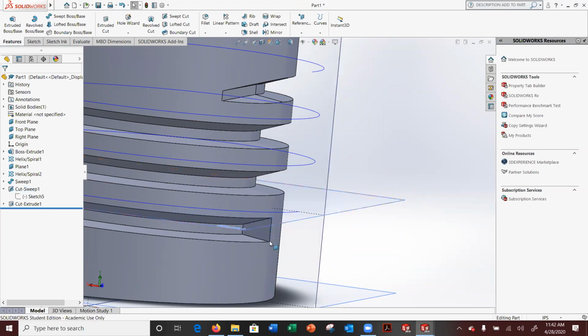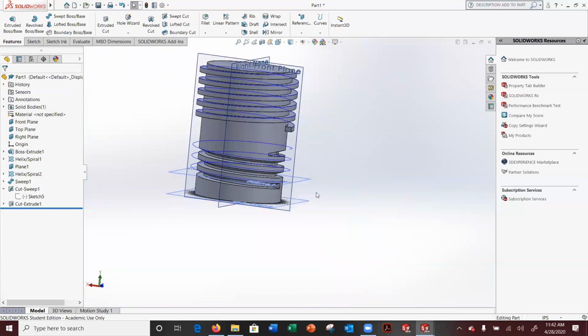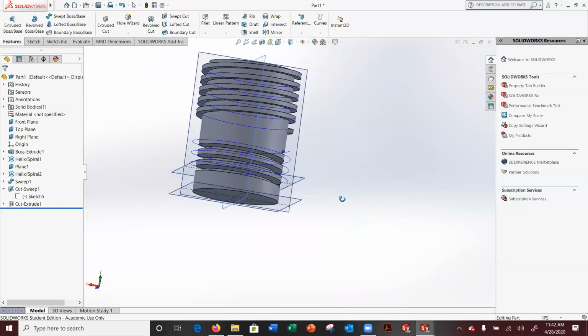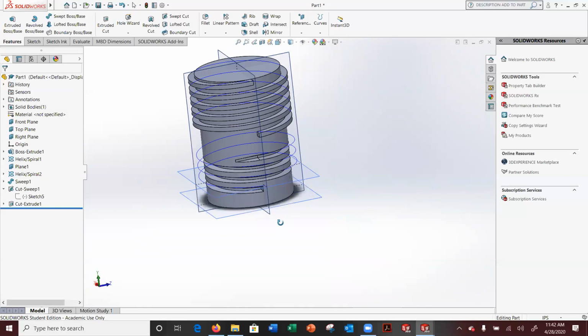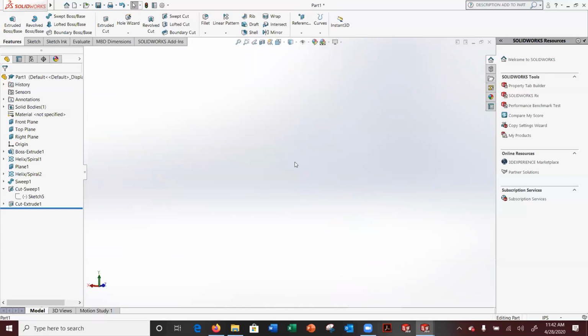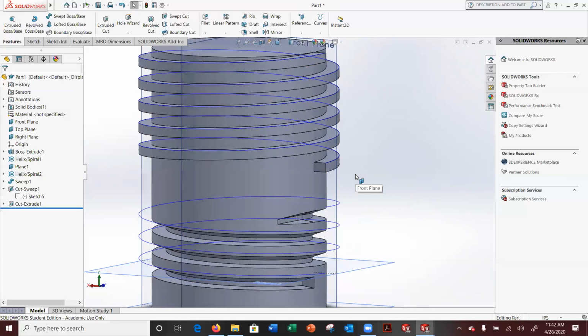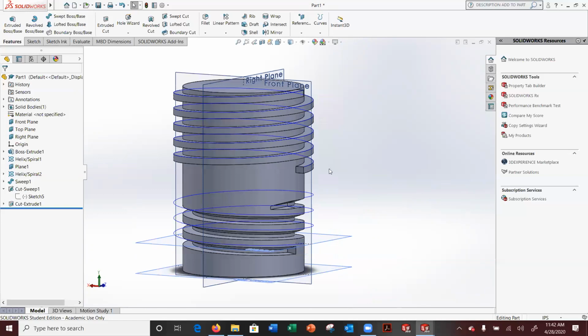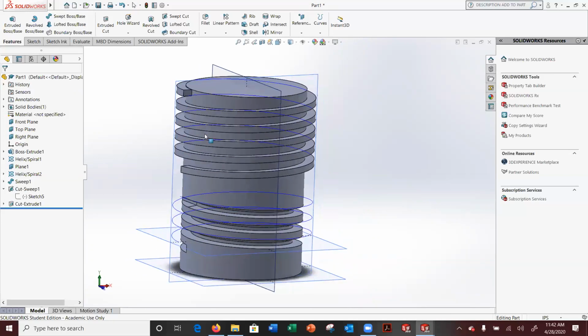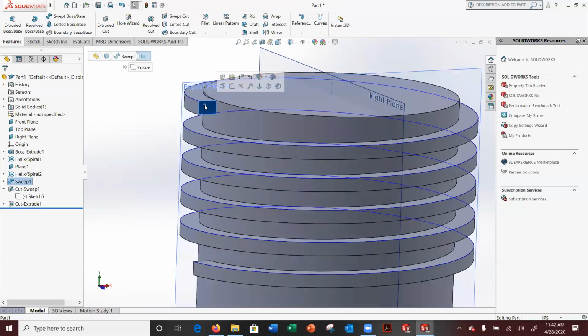You'd actually have to create another flute if you wanted to slowly flute out. So that's something to keep in mind. All right. And the same for the other end. Whoops. The other end, this shape becomes much more interesting if you want it to actually taper in. You'll have to create the other shape and create one of those loft so it ends correctly if that's what you want to do.